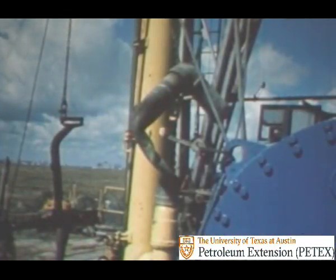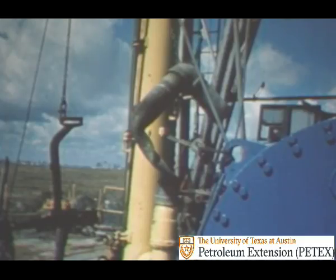The large yellow device is a mud saver, or as it's sometimes called, a Mother Hubbard. When a trip is being made, the saver is placed around the joint of pipe being broken out, and if any mud flows out of the pipe, the saver keeps the men cleaner and keeps the mud confined. Note the drain connection with the flexible hose. This drain is placed in a connection with the mud return line and returns the mud to the system.